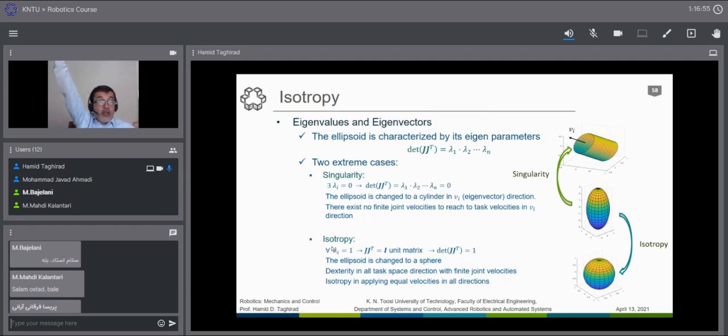When you are opening a curtain, when you are fully extending, this is another configuration for the same old hand that we have. Some places are good, we are close to isotropy. Some places are bad, we are close to singularity. And usually we are a mixture of that.